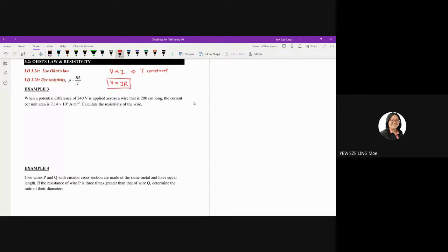After that, we look at what affects the value of resistance. You cannot say changing V will change R. You cannot say R is affected by I. Why? Because of this relationship: I depends on V and V depends on I. R is actually acting as a constant in this equation. So R is fixed as long as you're using the same resistor and you didn't modify it, keeping the same physical structure.